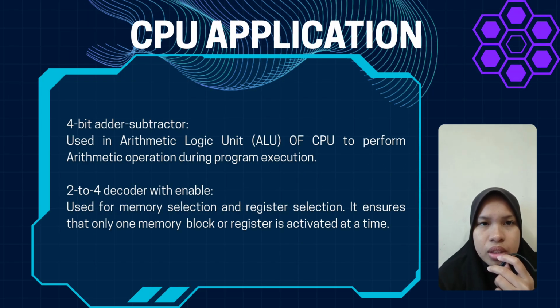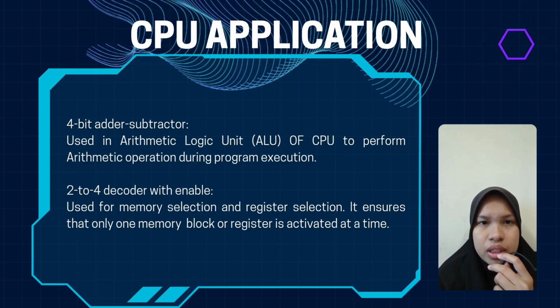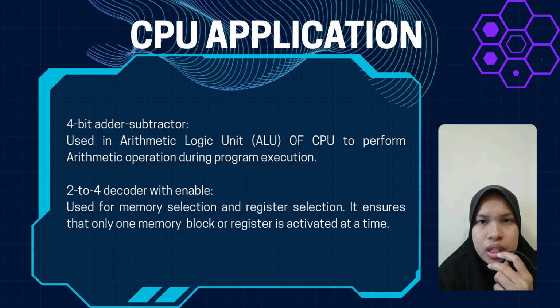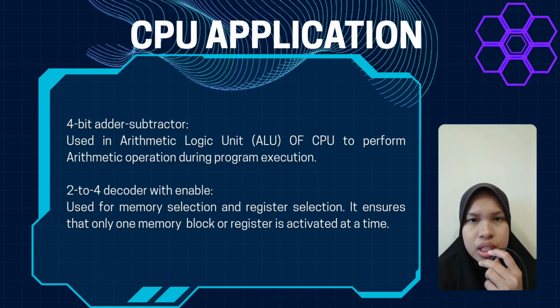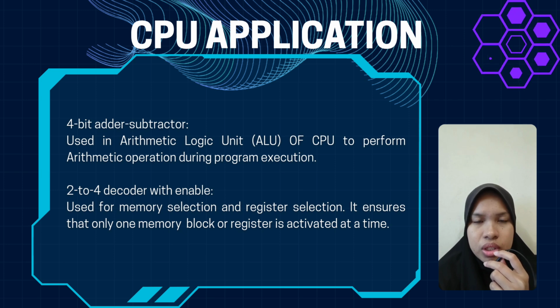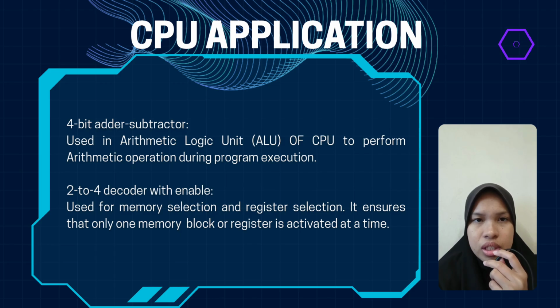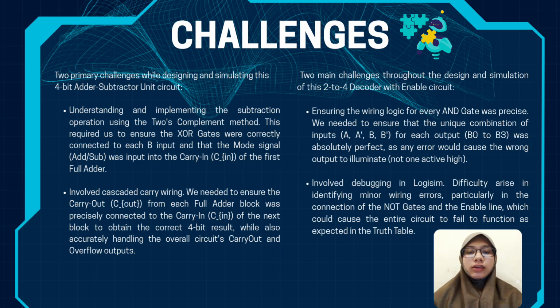CPU application: the 4-bit adder-subtractor is used in the arithmetic logic unit, ALU, of the CPU to perform arithmetic operations during program execution. The 2 to 4 decoder with enable is used for memory selection and register selection. It ensures that only one memory block or register is activated at a time.